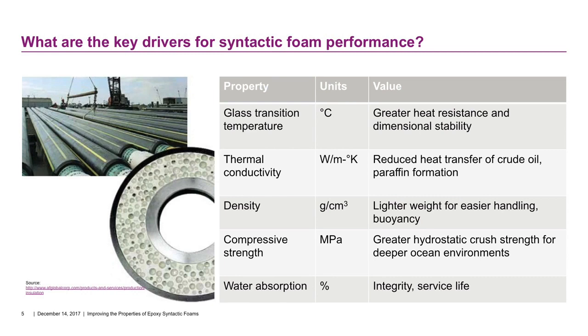What then are these levers, these key drivers for syntactic foam performance? These are the ones that we've taken a look at. First one is glass transition temperature, which clearly is related to greater heat resistance and dimensional stability of the foam, particularly at greater ocean depths.